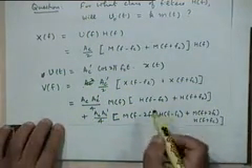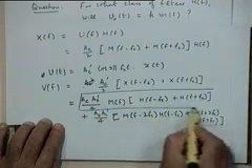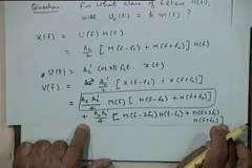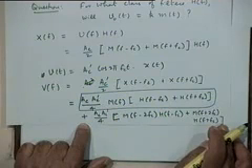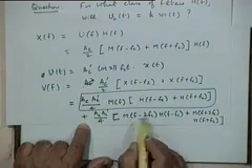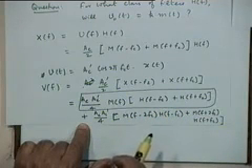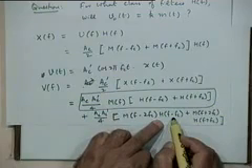So essentially what we are saying is this is the low frequency part of V of f and this is the high frequency part of V of f, which will be centered around 2fc, and you can see that this is obviously centered around 2fc because M of f was a low frequency spectrum, so you are shifting it to 2fc. What about H of f minus fc?